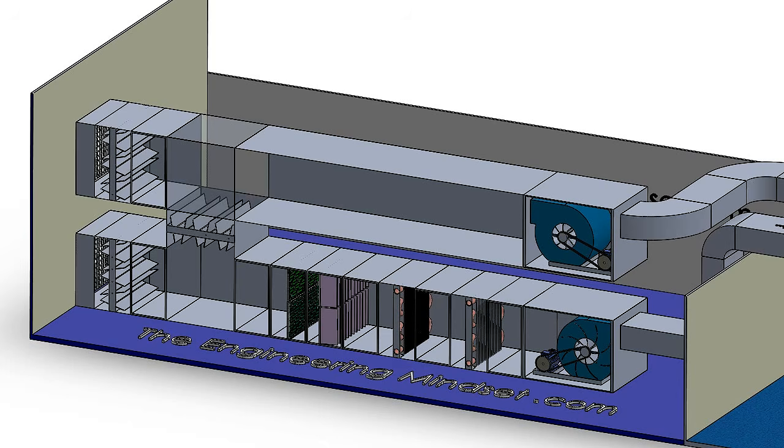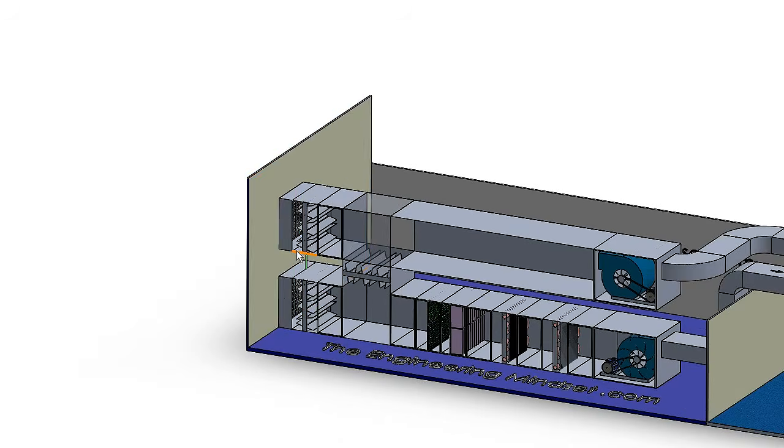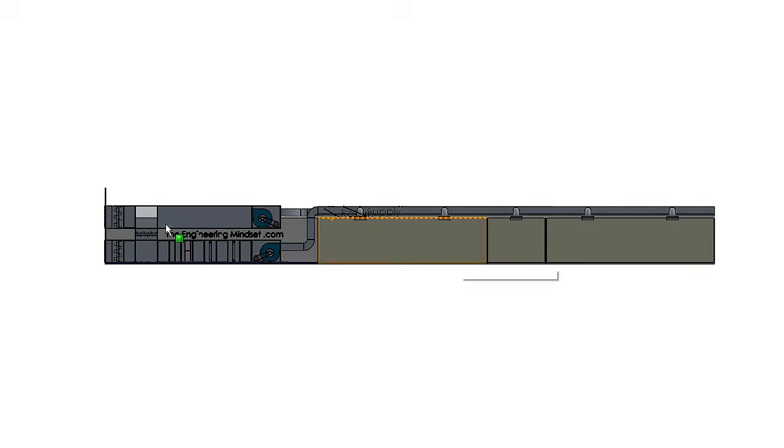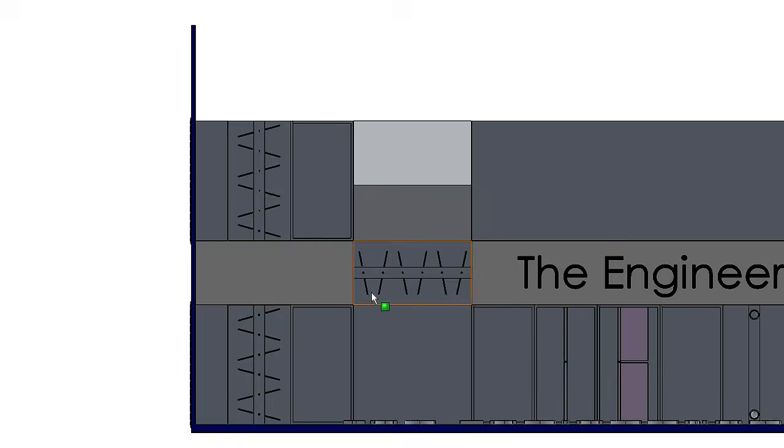So one of the first points I'm picking up there, and really drumming on a bit, is these dampers here. Let's just look at that from a better perspective. So we've got the dampers here, and these will all be connected via controls. In this example, I've just mechanically interlocked them, so that as we open them, they will all begin to close.